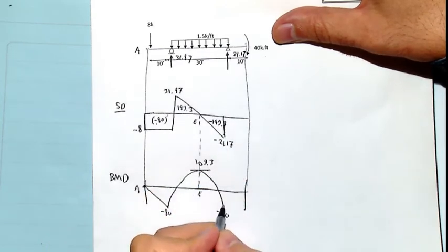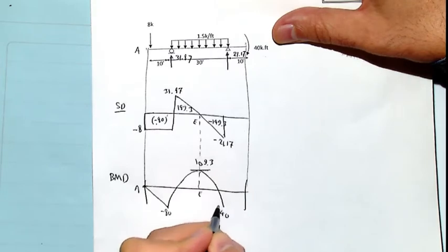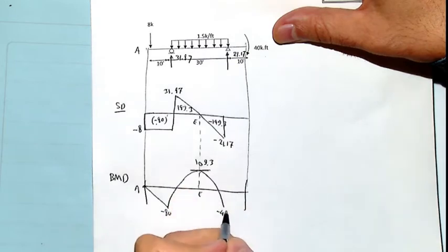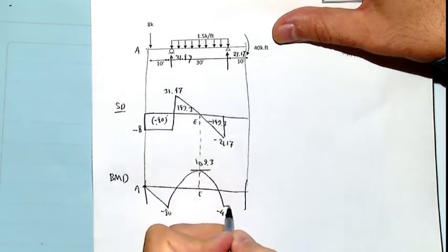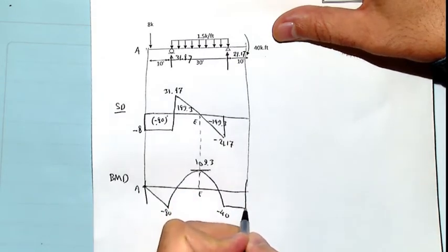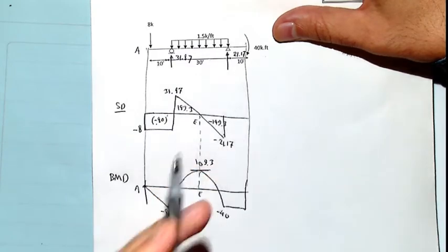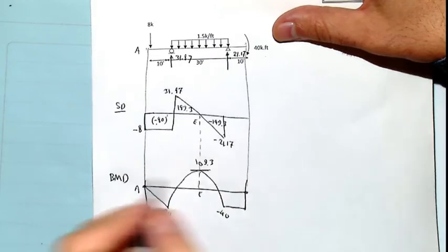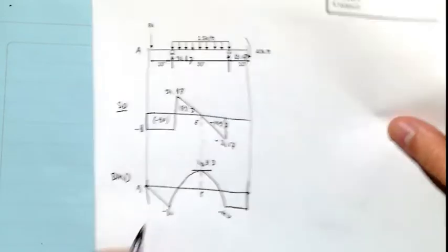So we continue at the same level as E's, because the moment diagram is a cumulative calculation of areas. So the accumulated value so far is minus 40, and we keep continuing up to the end, and we have positive 40 from minus to plus, reaching 0. It shows that my calculation is correct as well.